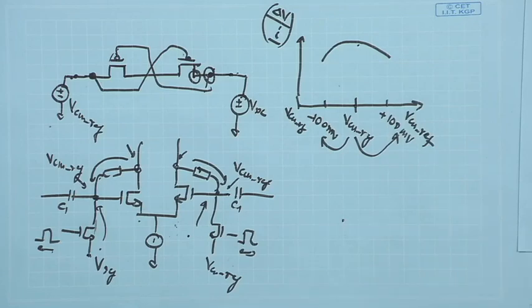It should be 1 second approximately. Because if you remember, we have used this in our earlier simulation when we did not consider the chopper operation and all. If you are just looking at the low cutoff frequency of around 0.5 hertz to 1 hertz to allow the content of the signal to pass, in that case the cutoff frequency was chosen as around 1 hertz or lower than that, close to that. So accordingly, the RC time constant will be close to that.